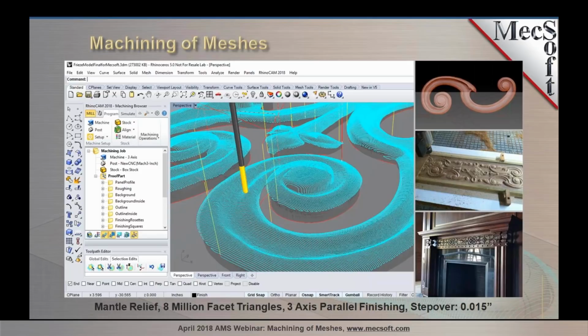So getting that number down, you don't need to have a lot of triangles in there to have a really clean model. You just don't need to, and you get a much, like you say, it's not cumbersome to work with, and you get a smoother, cleaner finish when it's machining. Mm-hmm. Yeah. So